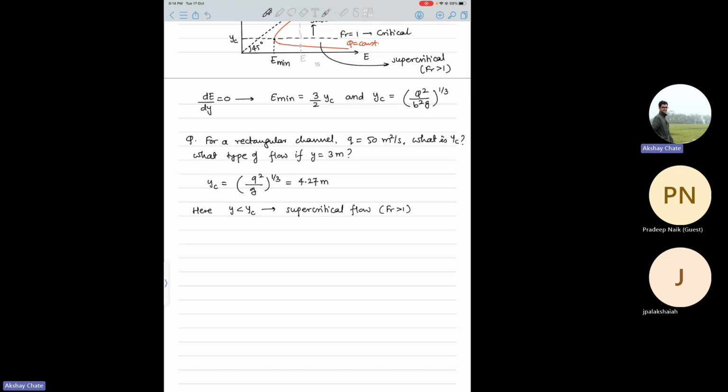Nice derivation is there, I'll go over it, but basically in a hydraulic jump, supercritical flow turns into subcritical flow, and that is only when a hydraulic jump takes place. Mostly the hydraulic jump phenomenon is governed by the Froude number existing at the supercritical regime, which is upstream.